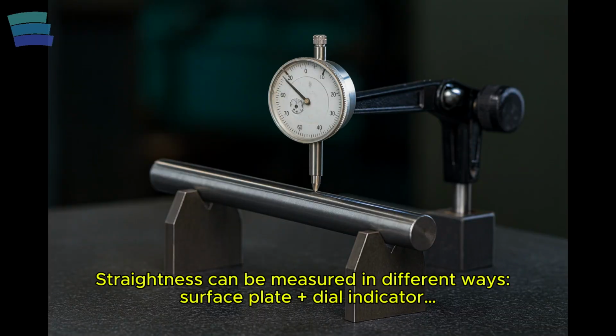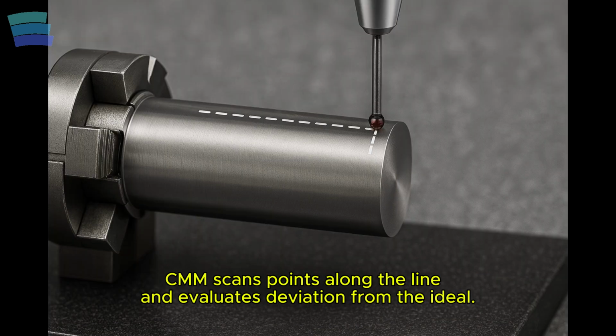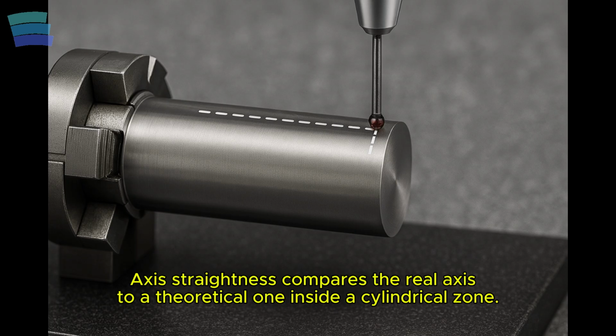Straightness can be measured using a variety of methods. Classical method: the part is placed on a surface plate and a dial indicator scans along the line. The difference between the highest and lowest readings is the straightness value. CMM method: points along the line are collected and deviations from the ideal line are evaluated. Axis straightness measurement: the axis of a cylindrical part is compared against a theoretical axis. The tolerance zone is imagined as a thin cylindrical shell surrounding the axis.